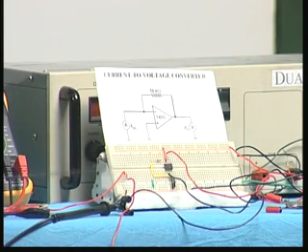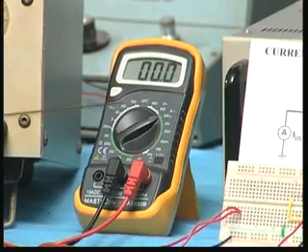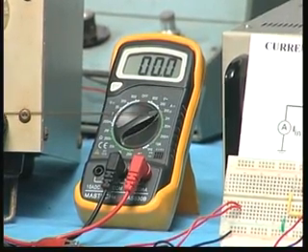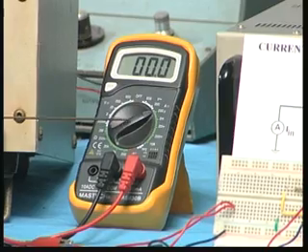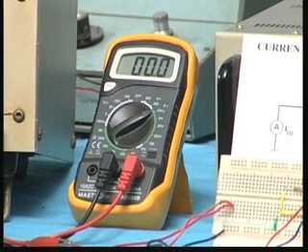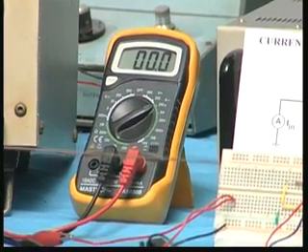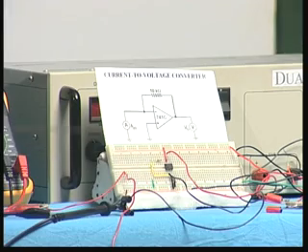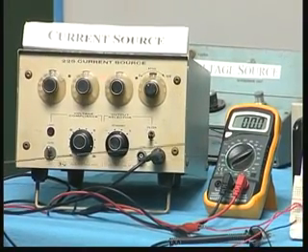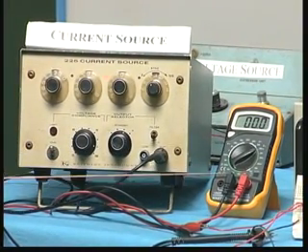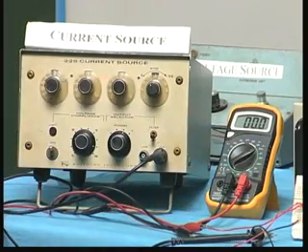To measure the current, I have introduced a current meter, another multimeter. I have selected the 200 microampere range here, and therefore what it measures is the input current. This comes in series with the current source, and then it is applied to pin number 2. This black wire is connected to pin number 2. So these two are connected in series at the input. This is the current source, this is the current meter which is measuring the magnitude of the current, and the voltage is measured using the output voltmeter.